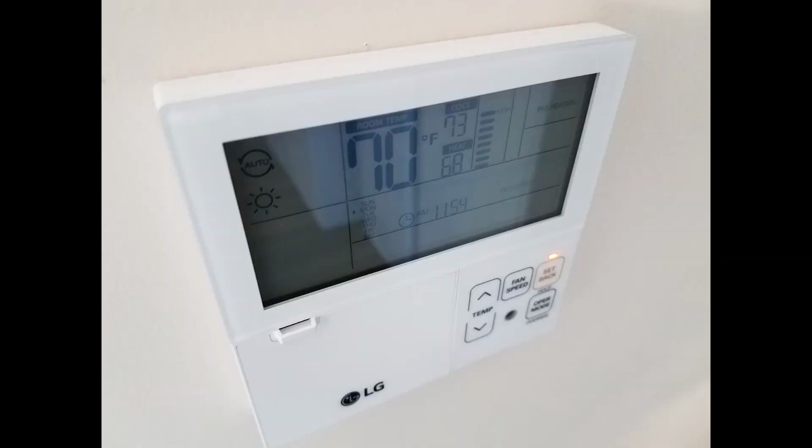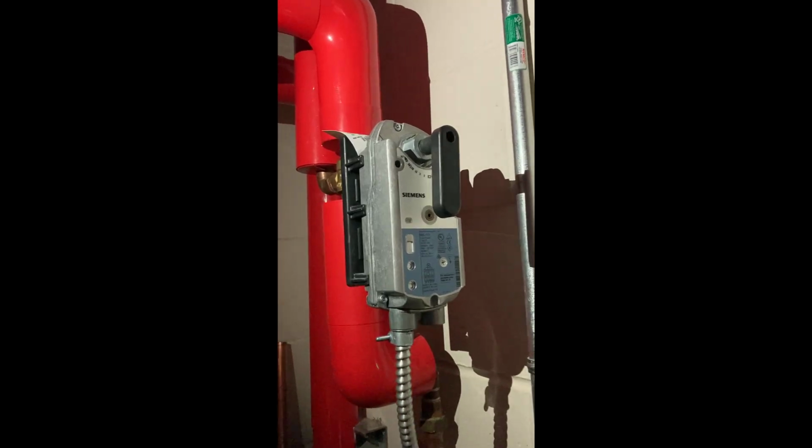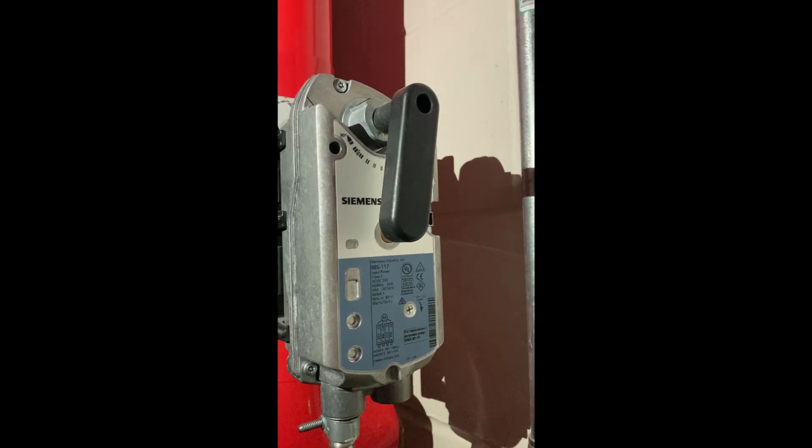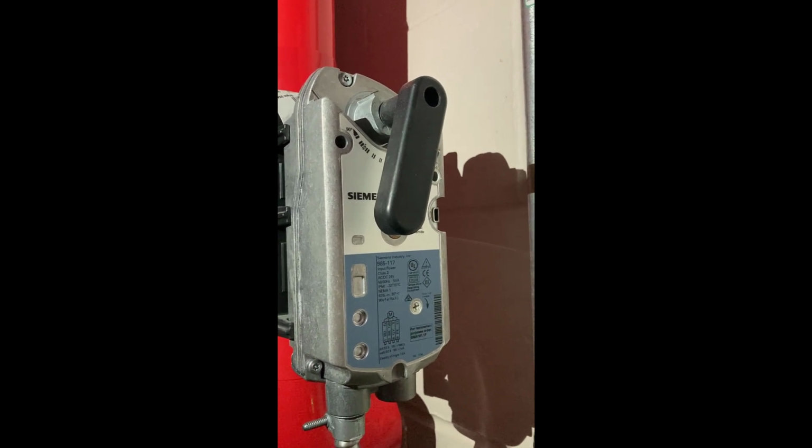You could probably figure out the rest of the story from here. The sensor begins to sense the boosted temperature. As the higher temperatures approach the programmed set point, the controller activates the actuator again. This time, the actuator physically begins to close the valve and may eventually fully close it.